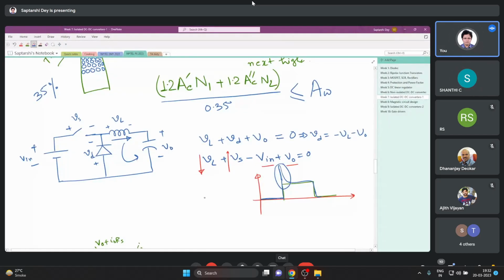During this time, there is some energy lost in the switch, and you need either a snubber, or maybe a heat sink, or maybe both. A snubber does not reduce the loss; it simply shifts the loss from the switch to itself, so that the switch is not damaged. The switch voltage looks like this.